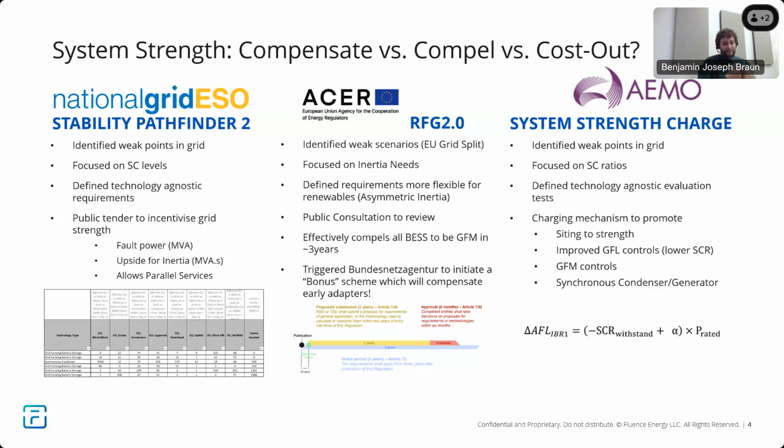Basically, this says as a renewable plant or as a battery, as a non-synchronous generator, you are not supporting system strength. You're even, in a way, consuming system strength. And in order to run the grid reliably, AEMO or the local TSOs need to somehow procure equipment to ensure that that stability and that system strength is guaranteed. That costs them money so that you can get on their grid and make money. So it seems fair to say that maybe you should have to pay a system strength charge for that.